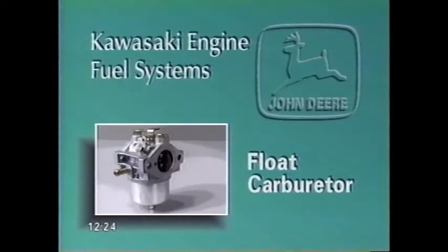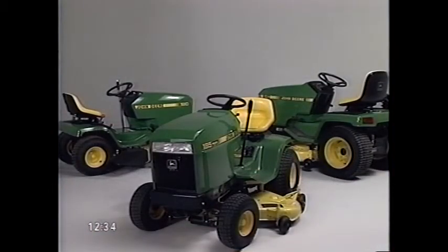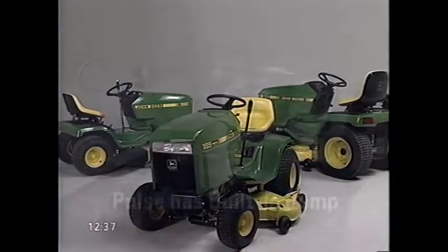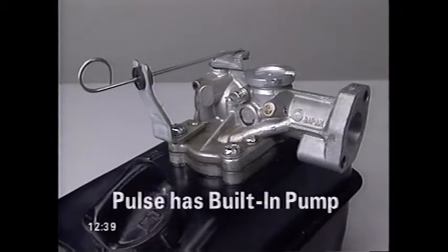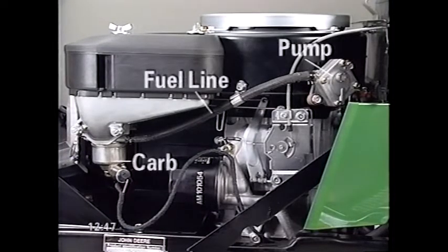Now, we are going to examine the principles of operation of the float-type carburetor used on Kawasaki engines. The float design is usually installed on larger equipment, such as lawn tractors. As you now know, the pulse type has a diaphragm fuel pump built into the lower body of the carburetor. That's not the case with the float type. If the system needs a pump in addition to gravity feed, it will be mounted separately and will send the fuel to the carburetor through a fuel line.